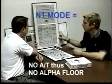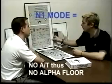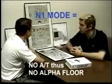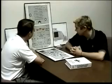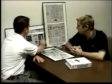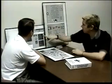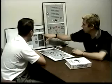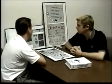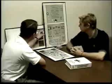Would you have auto throttles available in N1 mode? No, auto throttles are not available when I'm in N1 mode, and therefore I lose alpha floor protection. How do you know you're in N1 rated versus N1 unrated? In N1 rated mode, it's going to say N1 up here and give me percentage signs and such. Unrated? Gone. Amber X's. Thus no overboost protection. Correct.